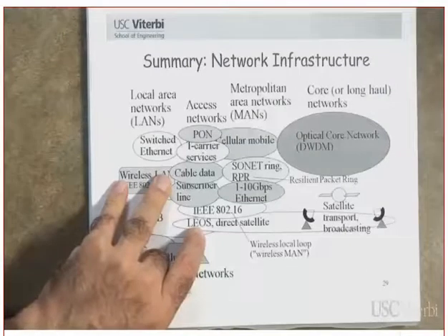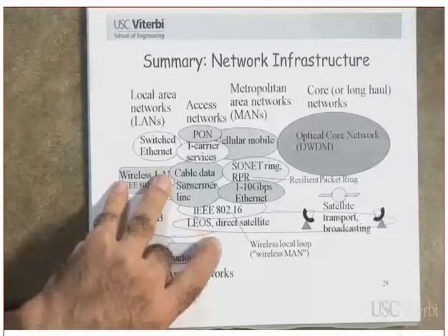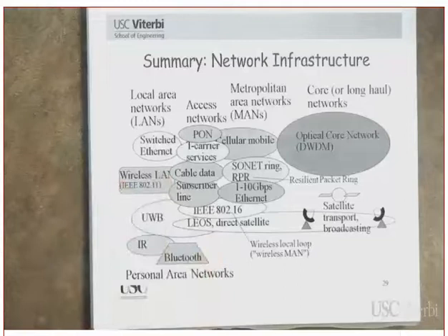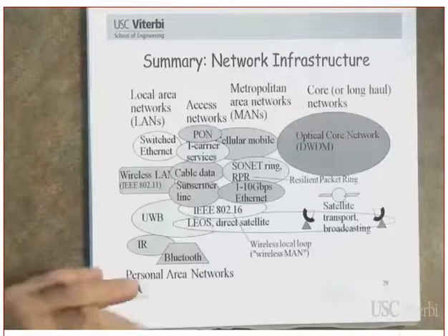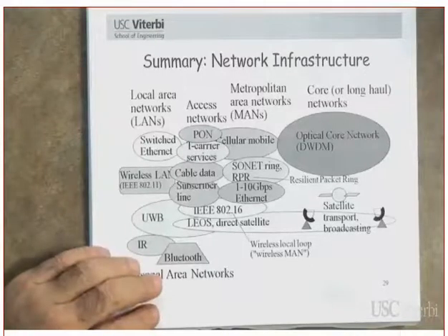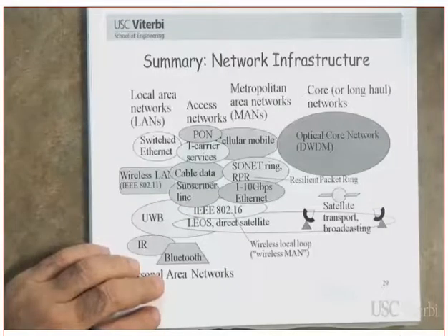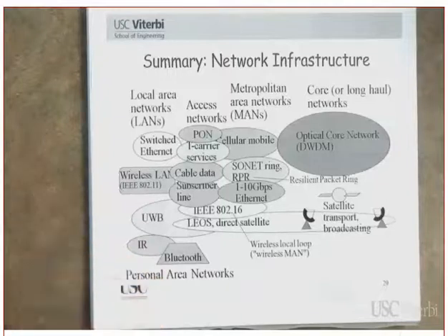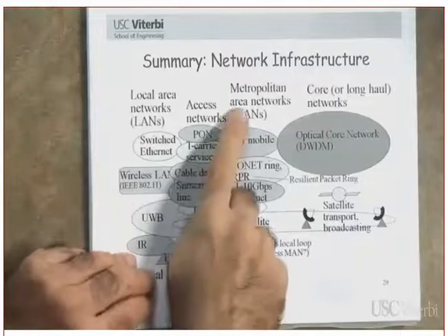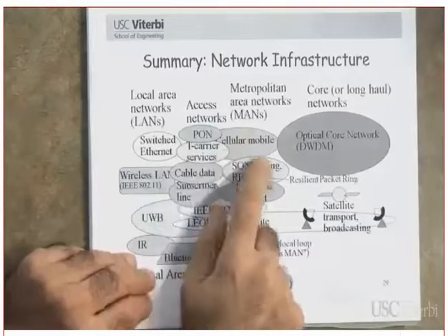The current successful satellite systems are the GEO systems. Always remember, as the satellite becomes what? Higher and higher in altitude, the coverage or the footprint becomes what? Larger and larger, which means you need fewer satellites to cover what? To cover the Earth. And why do they call it geosynchronous? Because that orbit is rotating at the same speed as what? As the Earth. So they seem to each other as what? As fixed in location.